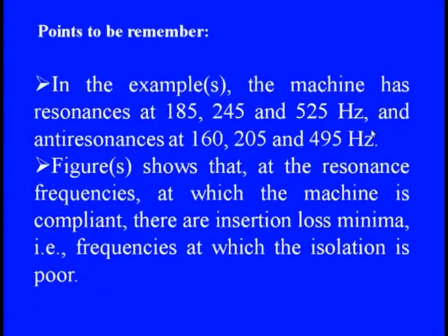the machine is compliant, and you see the minimum insertion losses are there. That means these are the frequencies at which the isolation is just poor. So when we adopt these things, we know how the isolators can be designed and what the possible resonant frequencies could be.